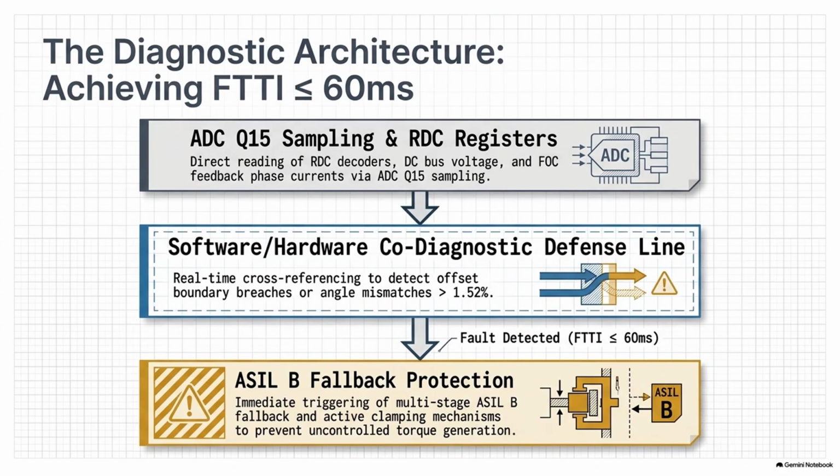Got it. The system takes that newly calculated offset and writes it into non-volatile memory, completely wiping out any manufacturing tolerances, thermal shifts from yesterday, or software calibration errors. It sets a perfect, customized zero baseline for that specific drive cycle. Okay, so the submarine knows where it is before it moves. But once you start driving, you're hitting potholes, you're heating up the metal, the magnetic mirage is happening. A baseline at 0 RPM doesn't help you at 10,000 RPM. How does it monitor itself dynamically while you're moving?